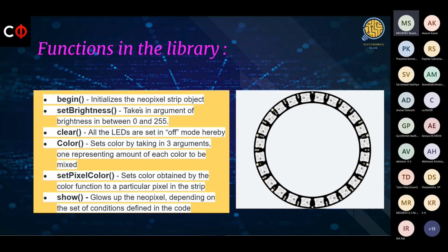Talking of which, I get reminded of a different thing. We'll be surprised to find that often in this NeoPixel library, the integers that we'd be obtaining by assigning the functions to a particular variable will belong to a data type of unsigned category, wherein we'll have only positive numbers. And again, their memory space has to be defined. In this case, we needn't define the memory space or the amount of space that we want to give it, because we've hereby told that it's 2 power 8.